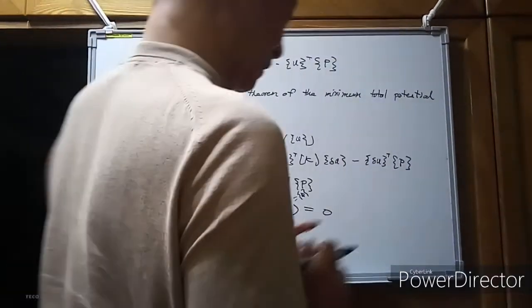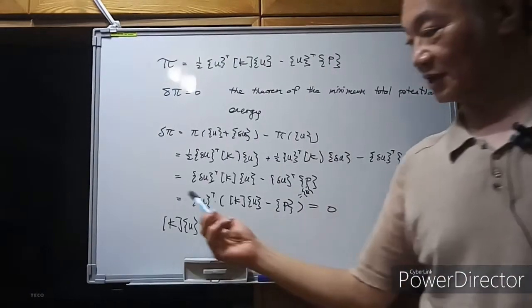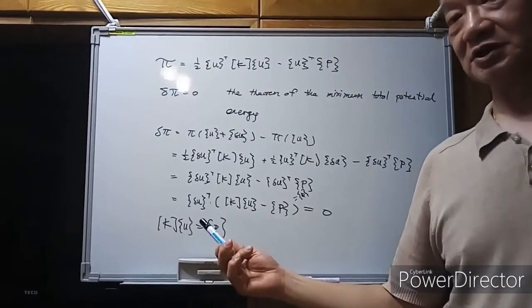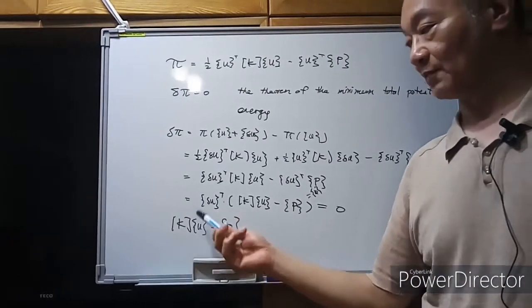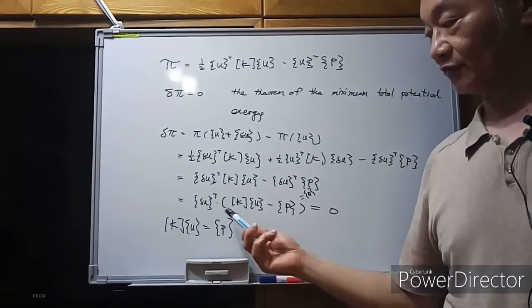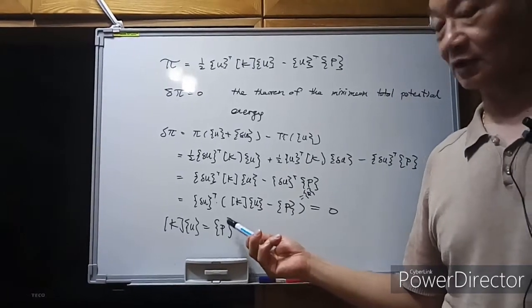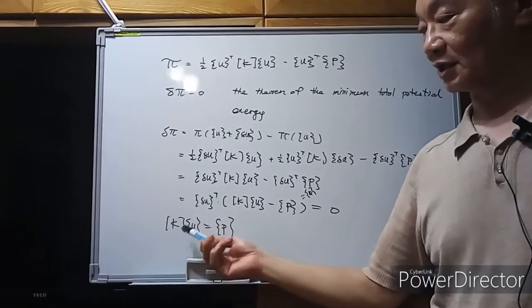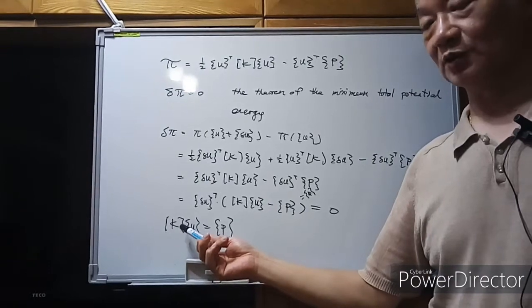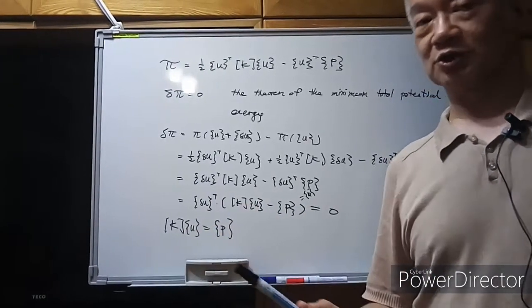So that's the next thing we need to do. If we know how to assemble the global K matrix, and you know how to modify the K matrix, and you know how to calculate the global load vector P and get the modified global K matrix, then you can go to the equation solver.